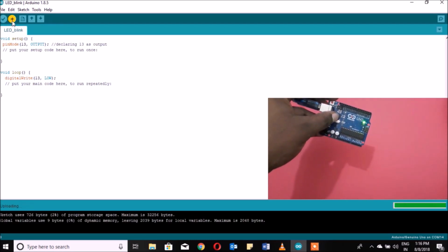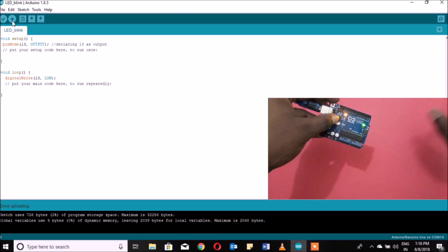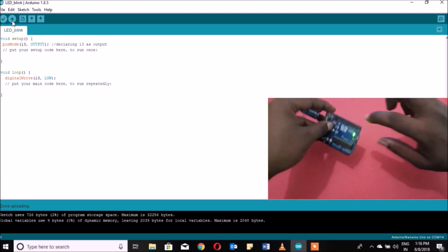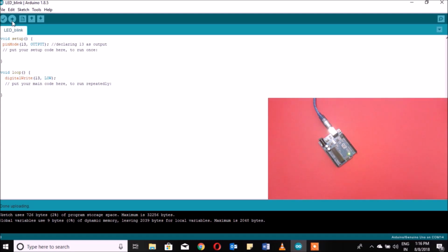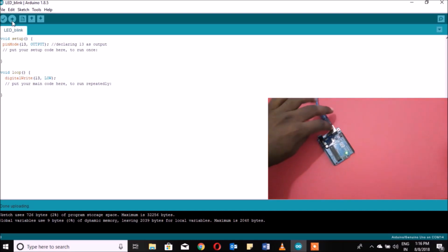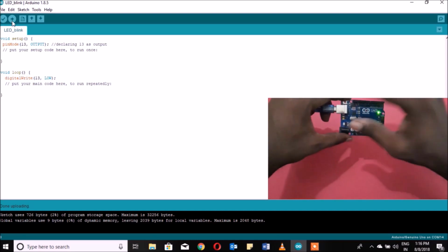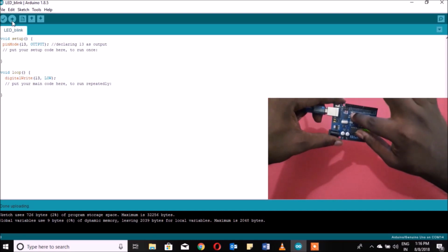Yeah, so you can see these two LEDs blinking. That is because we are making a connection between a computer and Arduino. As there is a communication, that uploading part is the communication. The computer is sending a code to Arduino using this port, using this cable, and as there is communication between this RX and TX, which is transmitting and receiving, they will blink.